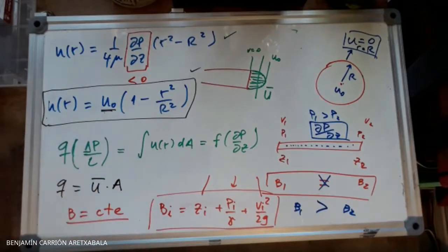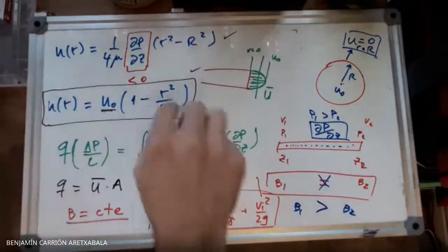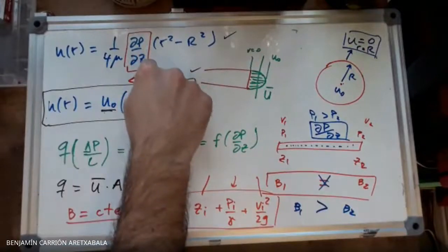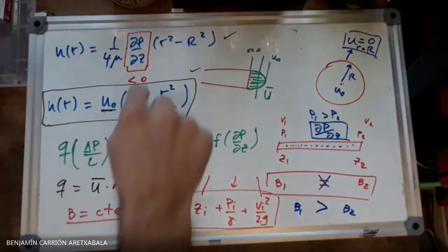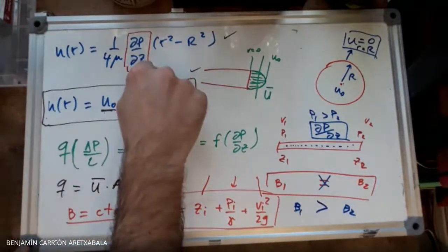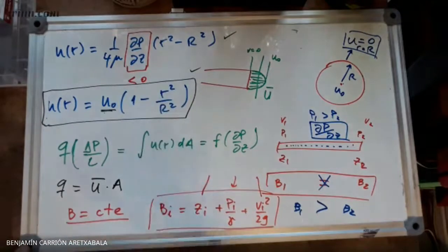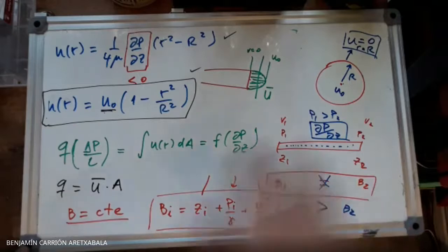So it's not easy to integrate. For all practical matters, we can assume this is a constant and it's just given. We could compute it, but that's beyond the scope of what we're doing here. You should know, though, that this change in pressure is due to viscosity. And since we have viscosity, we cannot use the Euler equation. That's why the Bernoulli at this point is larger than the Bernoulli along the line.